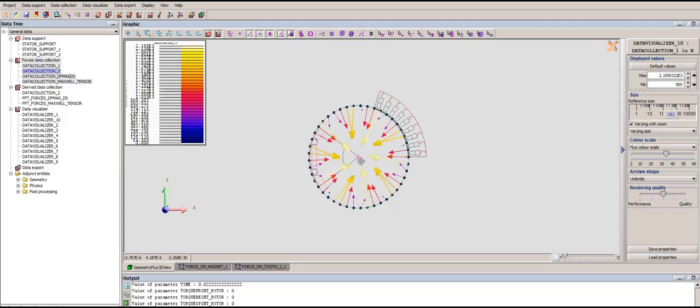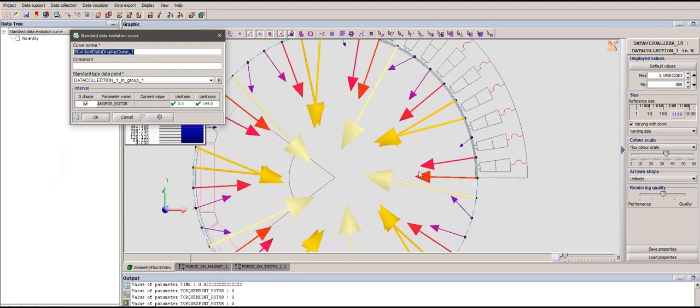And once I show the global force per tooth, like this, I can then go to the data visualizer and visualize the curve, right? For instance, I am going to select this group, which is the tooth, one here. And because I evaluated the force from 72 to 144, I have to select the same interval.